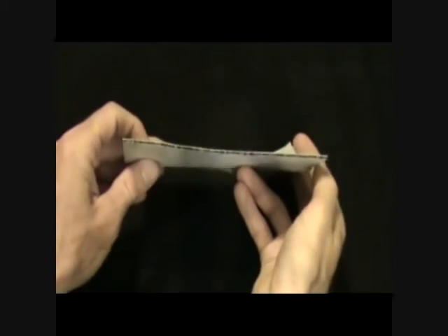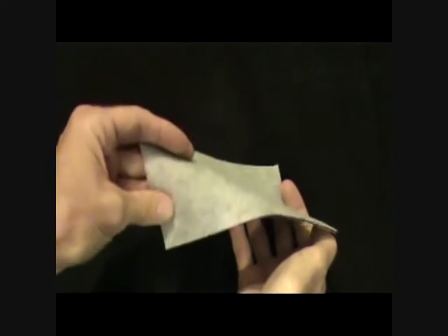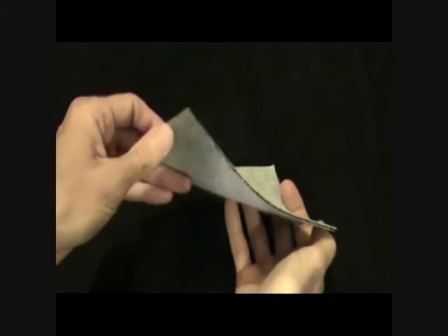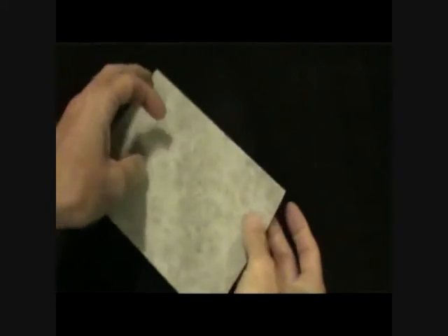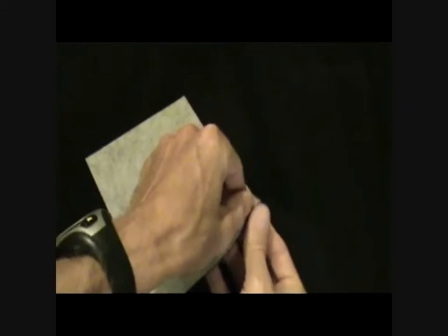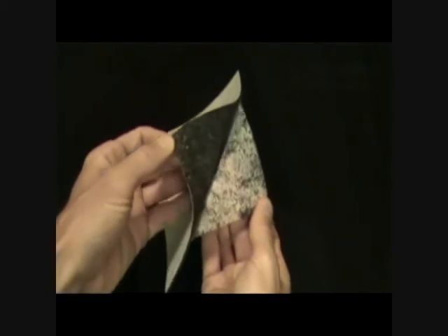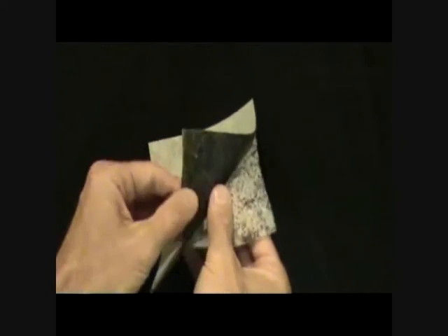Thermopore's polymesh adsorptive filtration media is comprised of 2 outer scrims that function as a wrapper for the material's internal adsorptive ingredients. In this case, the outer scrim is composed of 2 polyester nonwoven materials. But understand that we have design and manufacturing flexibility to use any number of materials as the outer scrim. Inside the scrim, you'll notice our adsorbent material. In this case, it's an activated carbon.